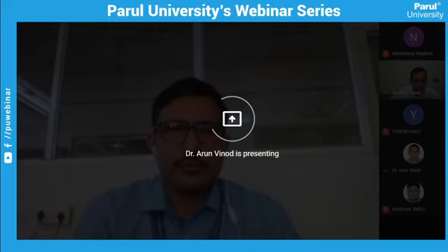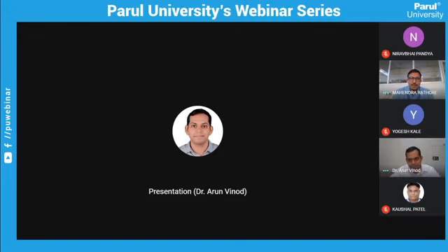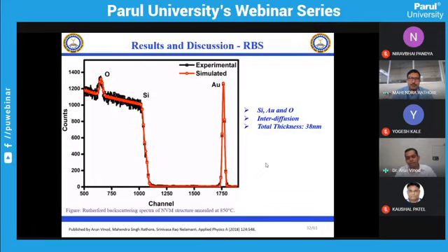Yes, sir. Here, how did you calculate the thickness of 38 nanometer? Sir, we have used a standard program called the RUMP simulation program, and with respect to this RUMP simulation program, we have calculated the total thickness to be around 38 nanometer. But the gold is in between the SiO2, Au, SiO2. Yes, sir, that's why we used the total thickness.